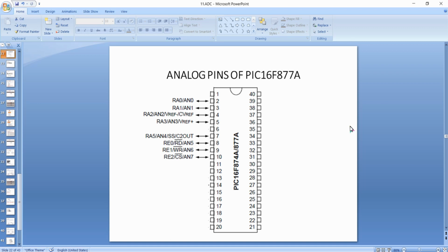That is, the analog DC voltage level will be converted into an equivalent step value inside the ADC peripheral of the microcontroller. And the range of step values that we will be reading from the ADC peripheral will depend on the resolution of the ADC peripheral available inside the microcontroller.